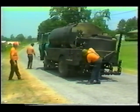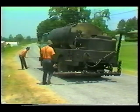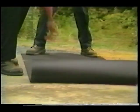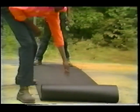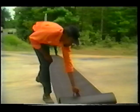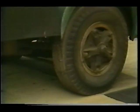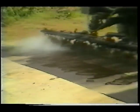Position the asphalt distributor at the starting point to apply the emulsified asphalt. In order to provide a straight edge at the beginning and end of the shot, place building paper across the lane just ahead of the beginning point and just past the end point. Then the distributor, traveling at the correct speed for the desired application rate, starts spraying on the building paper so that when it reaches the exposed surface, the application rate is uniform.